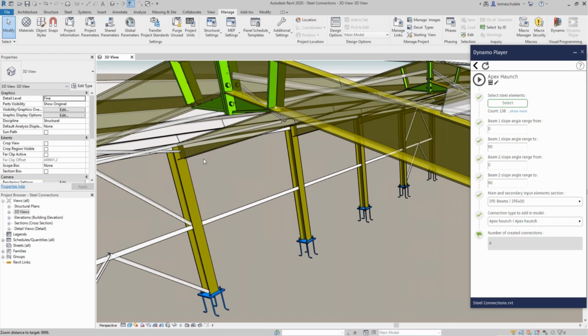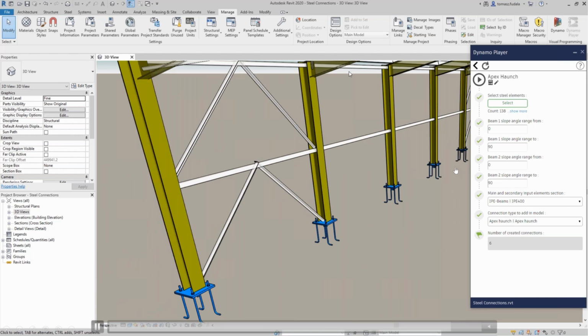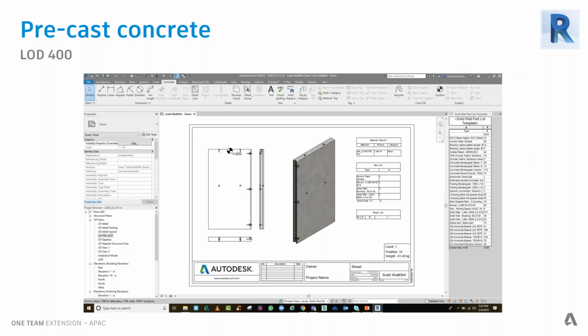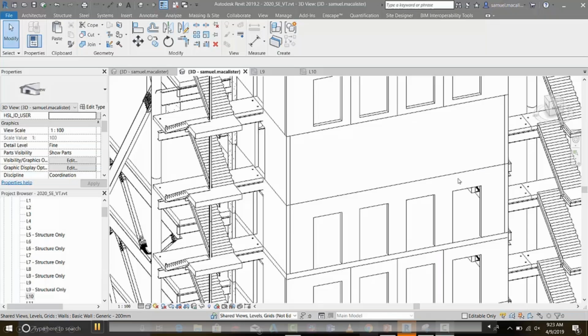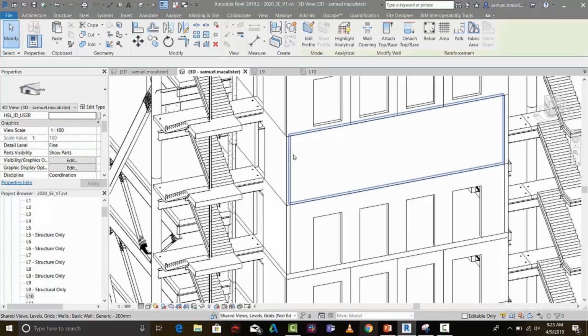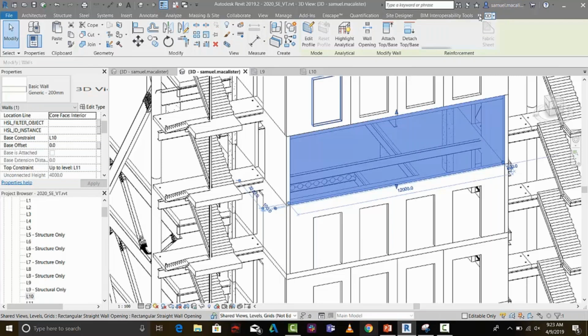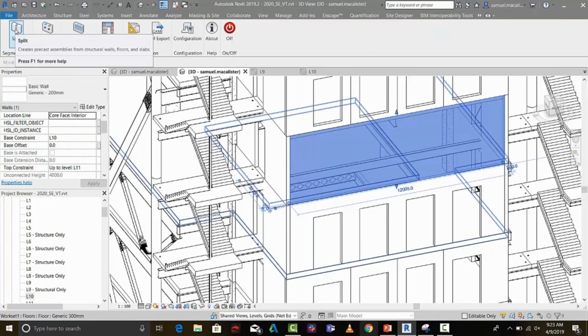The other enhancement that you see in Revit is the use of precast options. This really adds a lot of value, because now we can convert our design into a precast-ready model and even take it to any CNC machine output as well. So here you can see it's much easier. You have a Revit model, and all you have to do is use our precast tool. These precast tools are generally at the end of your ribbon, so you may need to click on the arrow keys to expand. And here you have the split, fabrication, reinforcement, and configuration tabs.